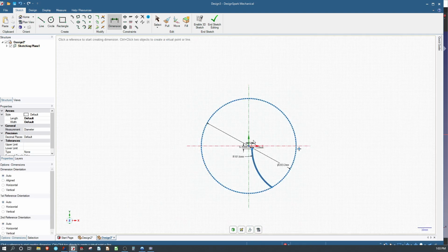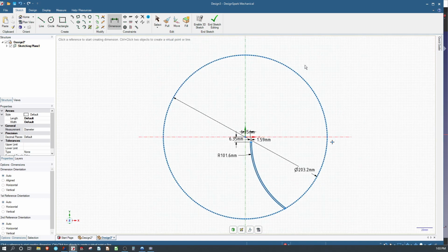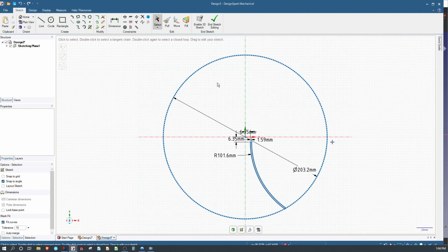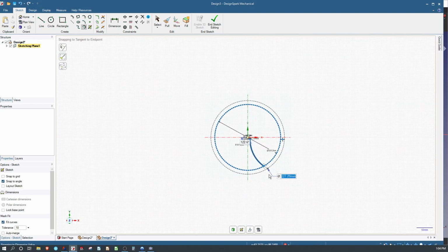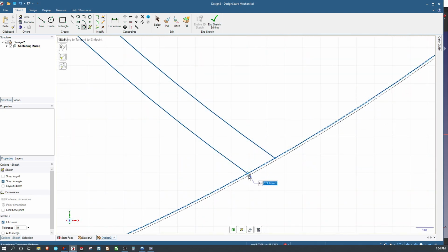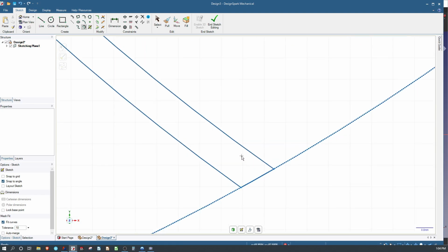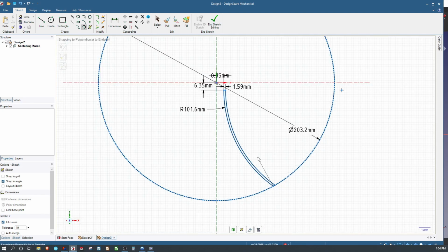Kind of big compressor. And you'll see that everything has gone from this cyan color. So if I draw a sketch element here that's like this cyan blue versus this navy blue, right? When things are fully constrained, they turn navy blue. When things are not constrained, they have a cyan color to them. Should, again, bring back a lot of memories of other platforms, right? The sketching environment really works the same like in other platforms. So I just made a 3-point arc that I drew to enclose this kind of blade profile that we're working on.